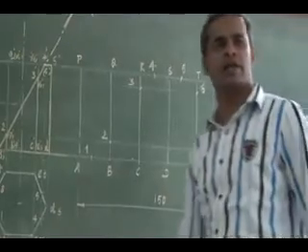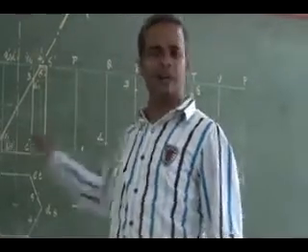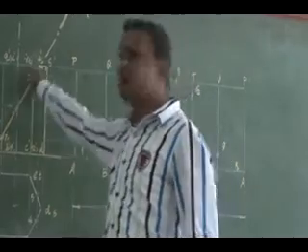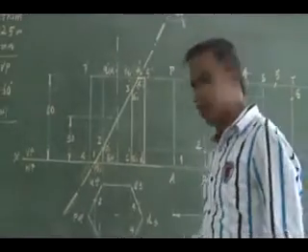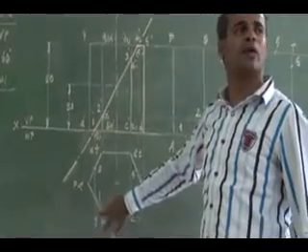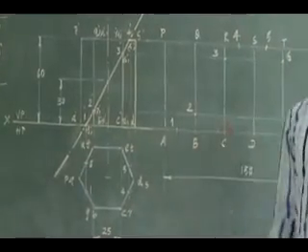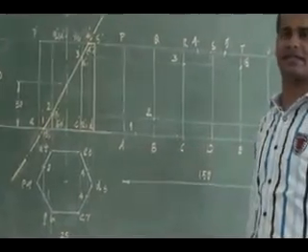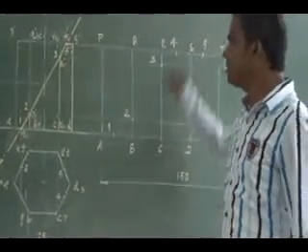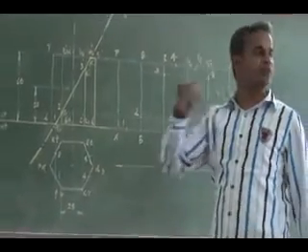Now, is it clear? If a cutting point falls on a vertical edge, it can be projected directly. If it falls on the base, it should be projected to the top view. In the top view only will I know the exact location on the base side. So that location has to be transferred properly onto the exact base sides, either the bottom base or top base sides. Is it clear? Do you have any clarification?